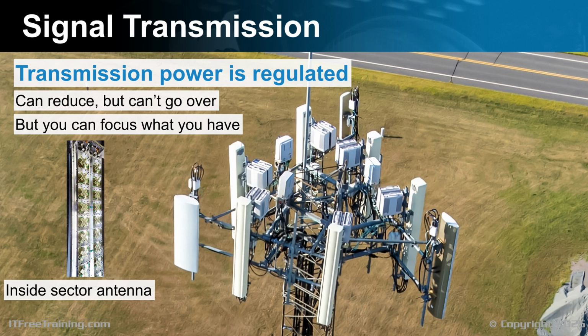Each little transmitter has a motor which can adjust the angle by a small amount. They are built with materials that obstruct wireless signals entering from the rear. This design ensures the transmission occurs primarily in one direction while blocking incoming signals from the opposite side. Due to this focused transmission, the antenna works at a specific angle directly in front of the antenna. To get 360-degree coverage, multiple antennas are arranged in a circular formation. You can understand now why you see cell towers designed this way.